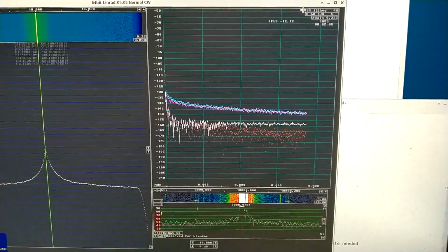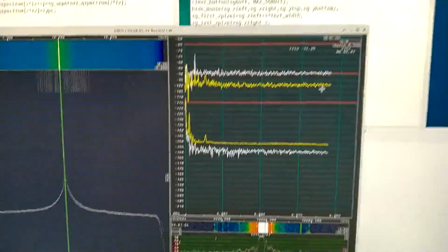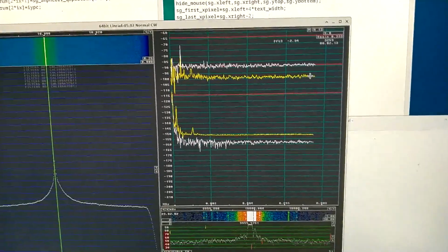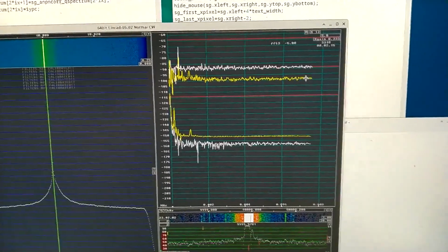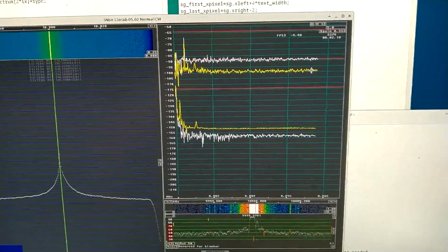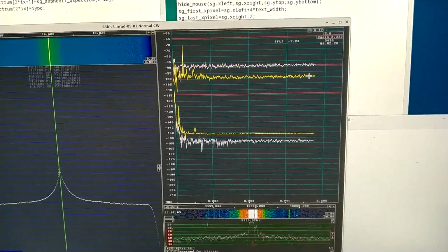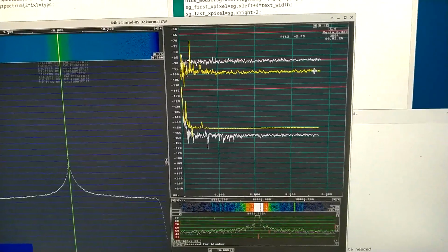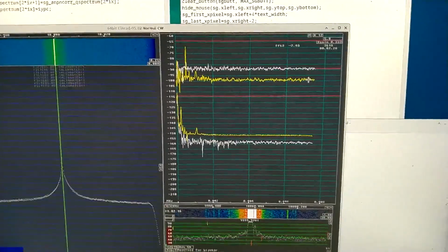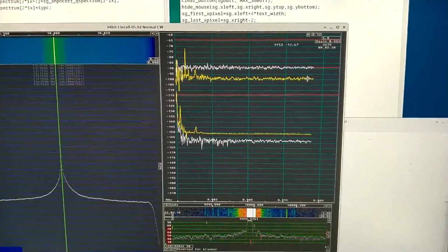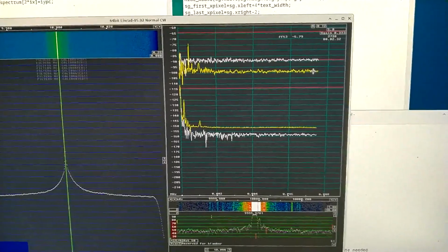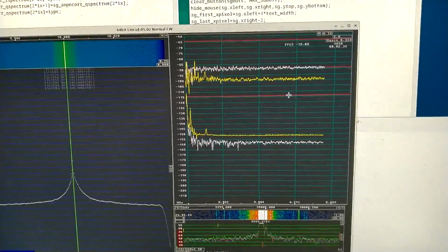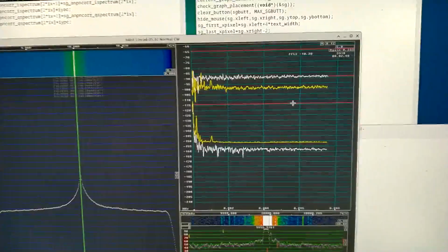But that's not really important. What I can see is that the remaining amplitude noise is very strongly correlated with the phase noise. So something could be done taking the information from the amplitude noise and use that to produce a phase modulation that would cancel the phase modulation. So if this is a general way to fix oscillators, it would be very important to know.